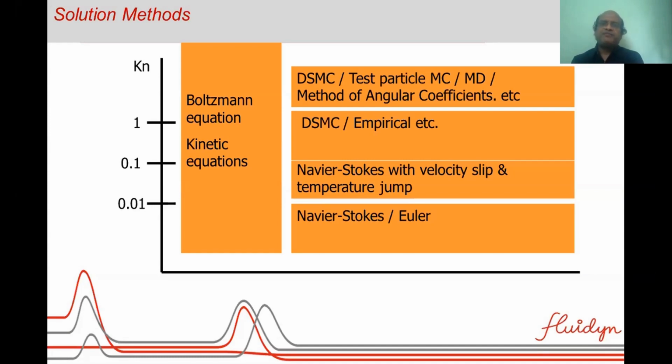And as the Knudsen number increases further, certain other methods are developed, and we had to go to a solution of Boltzmann equation or direct simulation Monte Carlo techniques.